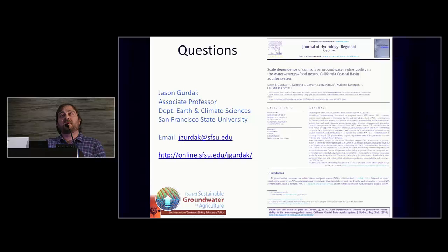So yeah, you need to be careful. If you're sampling from a public supply well that has a long screen, you're sampling groundwater over a much larger vertical distance, so that might have a different effect than if you have a monitoring well that has a very short screen and you're at a very low flow rate. So all those things are needed. Those understandings of how to collect a proper water quality sample goes into the reliability of your data and your redox conditions.